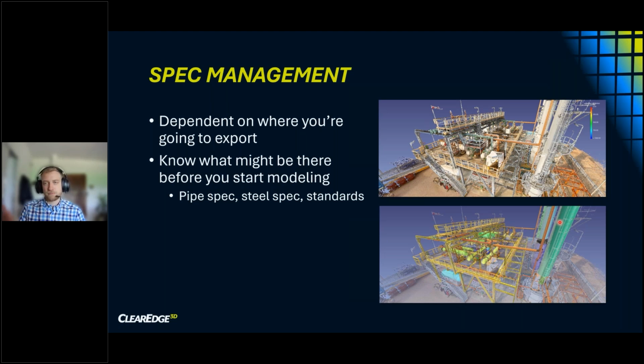There are restrictions. If you're going to Plant 3D, you can only use the built-in specs for EdgeWise currently. E3D, we're working on improving that workflow continuously, but that's actually a lot more flexible in some ways. And then Revit, we're making generic pipes with family objects, and it's really just looking at the nominal value, and after that, it's a standard family that you can switch out for the system type or the system. So that's the important one for piping.